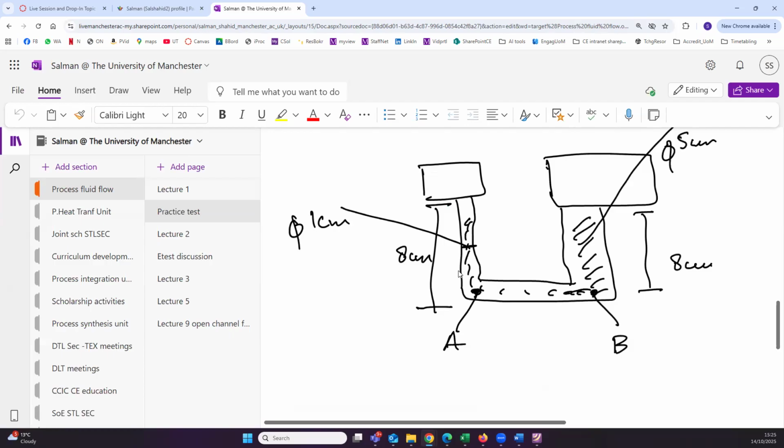Because if you remember, I showed you with this weird shape container that it doesn't matter what the shape of the container is, because what you are measuring is the weight of the fluid above this point and this point. So by making it bigger, it is not making any difference up to this point. Think about, for example, the sea, how wide the sea or oceans are. When you want to calculate how much the pressure will change, you do not take into account the surface wideness. You just look at the density of water.